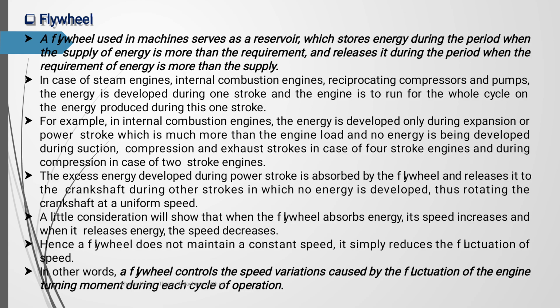The flywheel is mainly used to supply energy when the fluctuation of energy occurs in the engine system. The engine develops maximum energy only at the time of the power stroke, but in the remaining strokes the energy levels are very low: suction, compression, and exhaust.